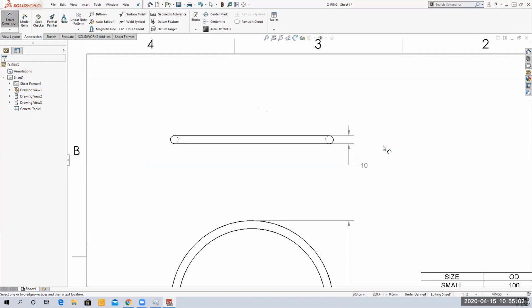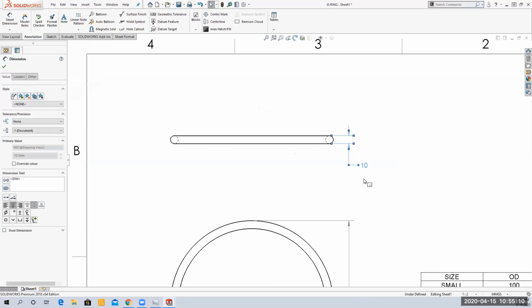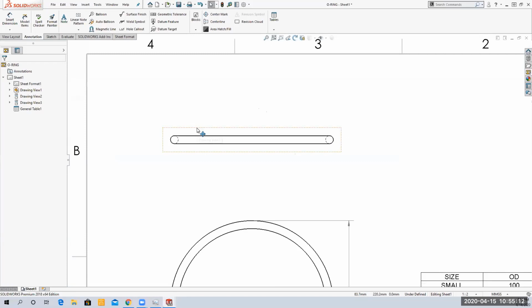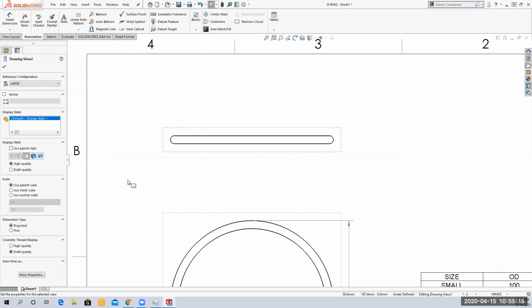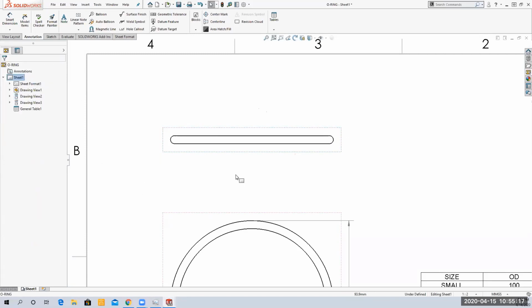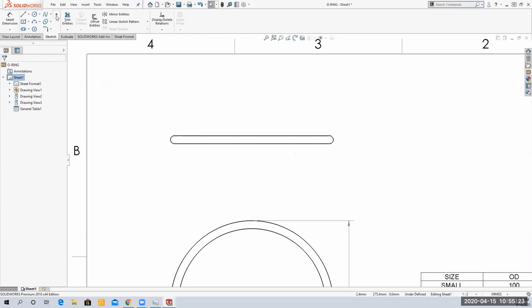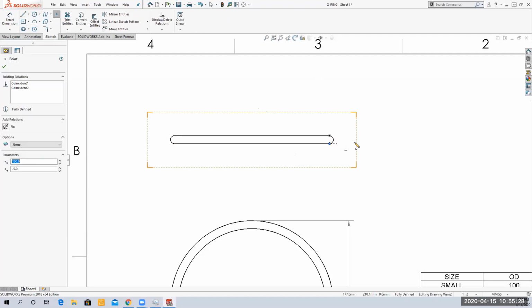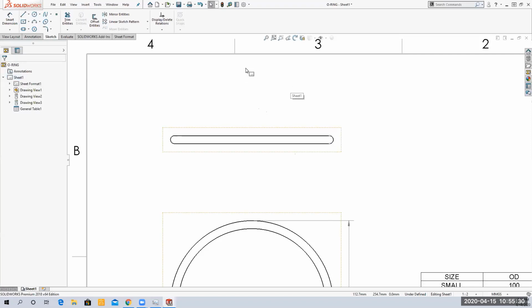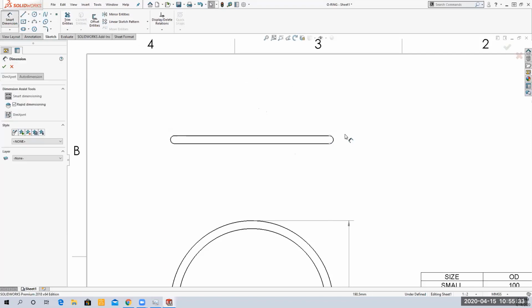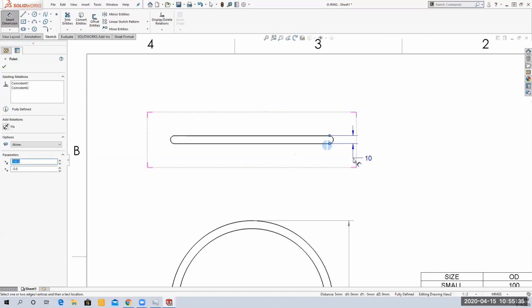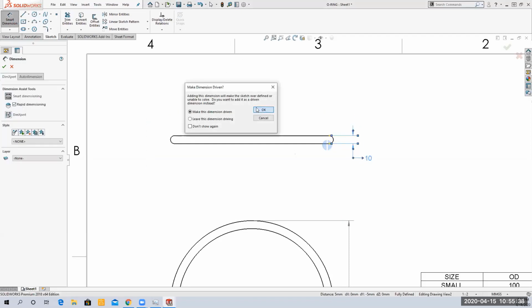Another way you can do it, I'll show you a couple different ways, because I realize that this top view can be kind of difficult, is I'm going to switch this back to hidden line. Another workaround is to go to sketch and select the point tool here and place a point here and place a point here. Okay. And then do a dimension from those 2 points. Okay.